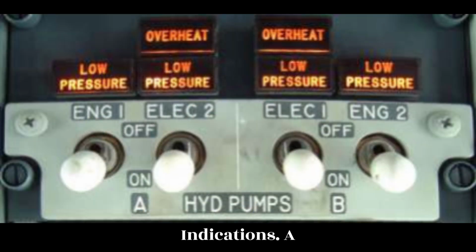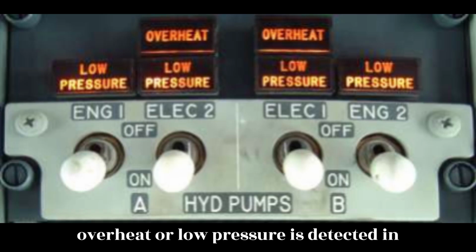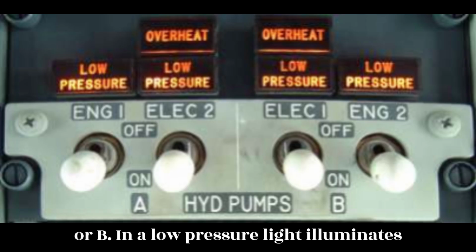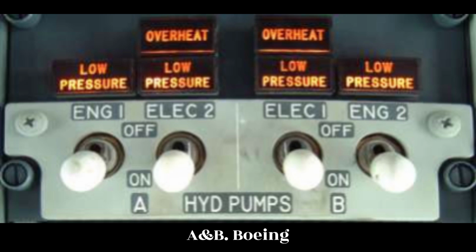Indications. A master caution light illuminates if an overheat or low pressure is detected in the hydraulic system. An overheat light on the flight deck illuminates if an overheat is detected in either System A or B, and a low pressure light illuminates if a low pressure is detected in System A and B.